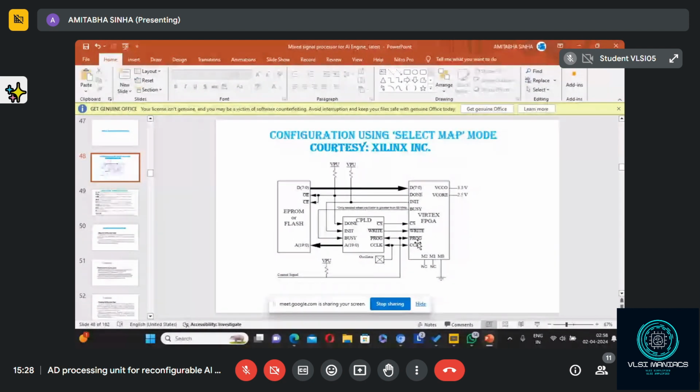Here, one line is there, the prog signal, prog bar. When prog bar is low, the FPGA is in the programming mode. When prog bar is high, the FPGA is not in the programming mode, which means it will be in the execution mode. Because the FPGA can work in two modes. Unless it is programmed, can it do any execution? No, sir.